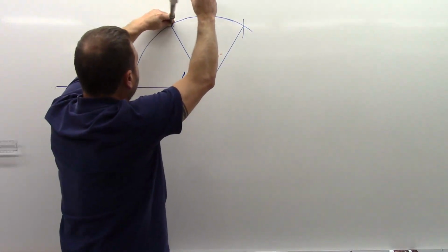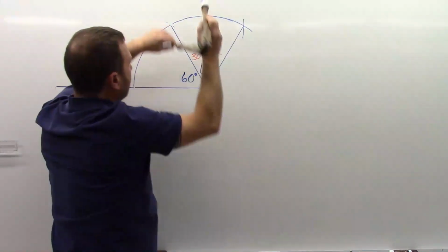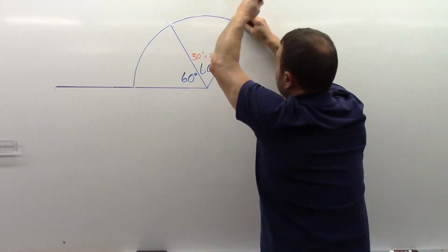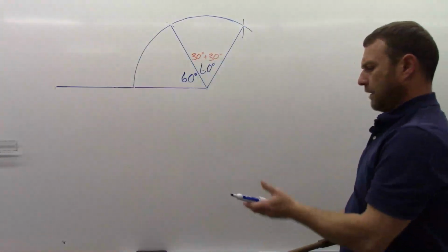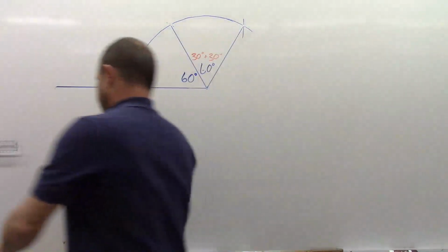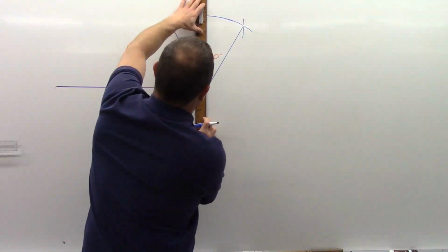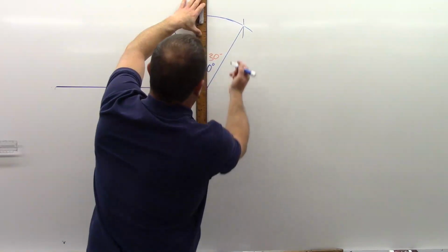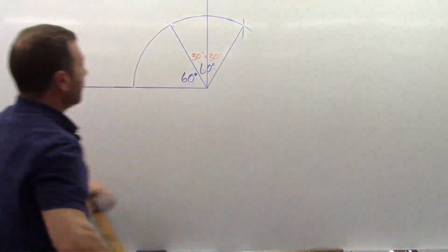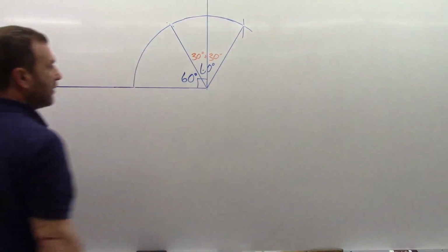So if I just cut this in half from up top here, and again, I've gone 3/4 of the distance of the arc, and I'll swing an arc above. This time, I don't need to go below. And I get 2 cross points up top because I already have the point down below. And I'll join that together. 60 plus 30 gives us our 90.